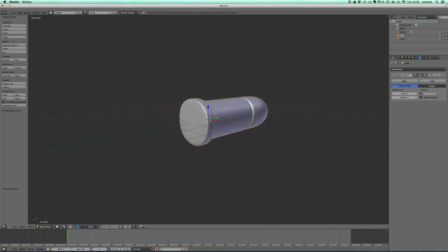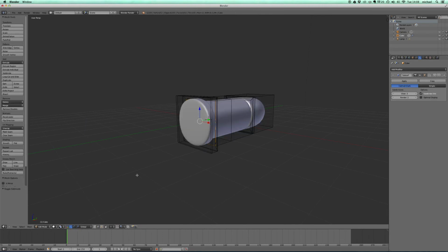So one bullet. Now I'm just going to do the end bit with the sort of the machining at the end. So I'm going to grab this face, and rather than putting edge loops, because if I put edge loops, I'm going to create like weird kind of things along here that will turn my bullet square, and I don't want to do that. So what I want to do is I want to do something called an extrude. So I'm going to extrude it, and then if I do it that way, it's going to go crazy, and I just want to do it a little bit, not much, just a tiny bit like that.